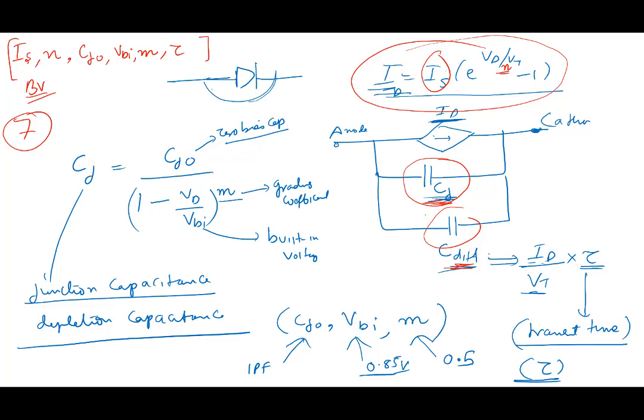All your semiconductor devices, transistors, MOSFETs, bipolar, if your mobile processor is not working very fast, why? Because the MOSFETs are not working very fast. Why? Because these capacitors are not getting charged and discharged. Ultimately, all speed issues come down to the capacitances, because the capacitance has to be charged and discharged.